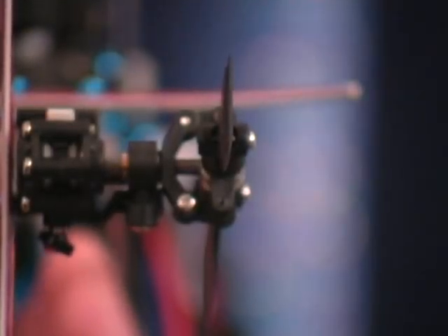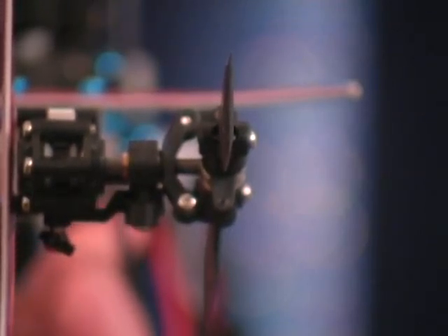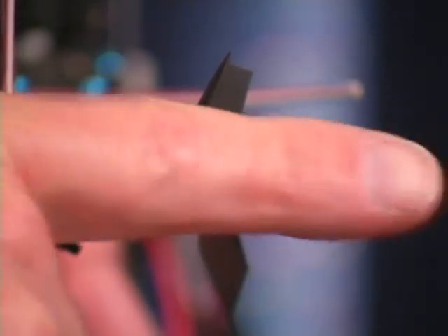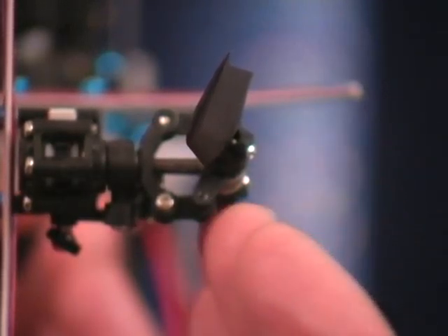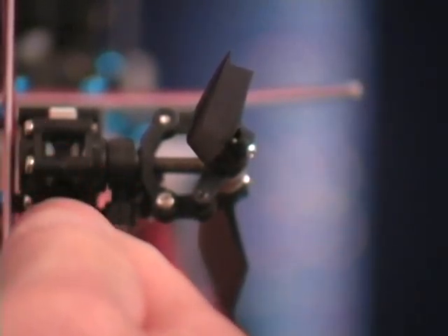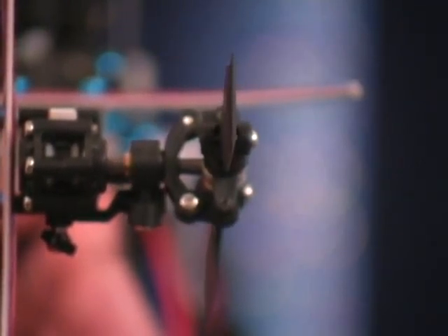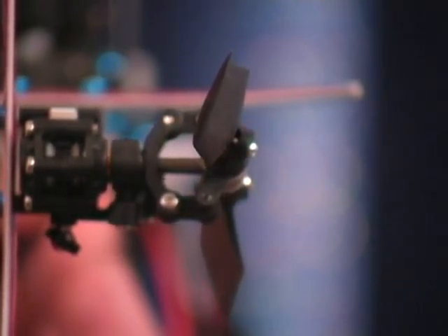As we start the tail rotor and gyro setup, first of all we have to figure out which way the push rod has to move to give right tail rotor. Or you could use left, I'm going to use right. So for right tail rotor, the tail rotor has to go this way, which will blow more wind to the right, which will push the tail to the left, which will push the nose of the helicopter to the right. So to give right tail rotor, the push rod has to move forward.